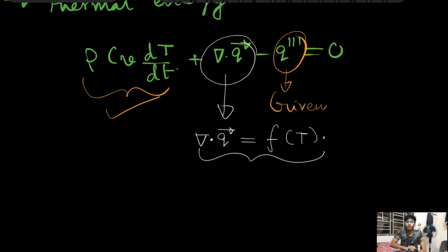So Newton's law of viscosity, what you have already studied, that is tau is equal to mu du/dy or mu del u/del y, anything. That is not the actual law. The actual law has come from the Stokes law of viscosity, and that is not mathematically that simple. But you should learn the derivation of that thing also.